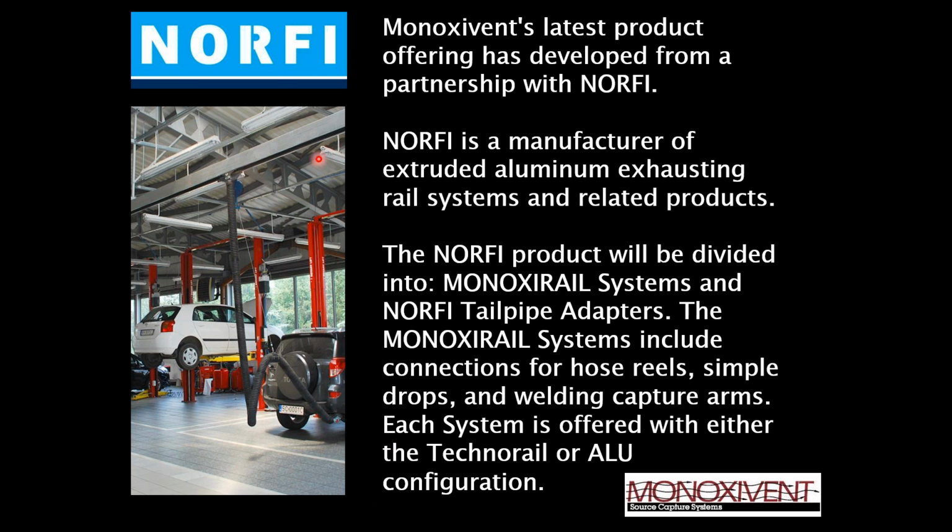So I have 3 drops. If my 8th bay needs a drop because it's running the vehicles, my first one goes down there, then maybe it's the 5th bay and the 3rd bay. So I position them. The idea behind designing a rail system is that no matter where my drop stops, it's designed to capture the design CFM. So in this particular case, it looks like it's all automobiles. That would be, let's say, 300 CFM. No matter where I stop along this bay, I'm able to capture 300 CFM and evacuate the exhaust through the rail to the ductwork and from the ductwork to the outside.